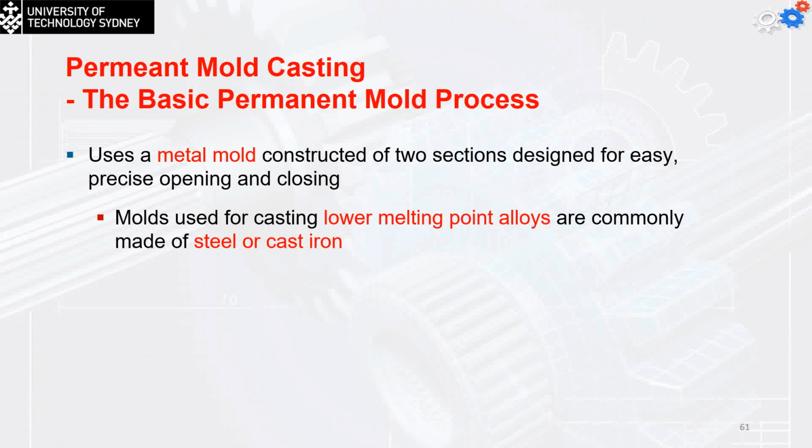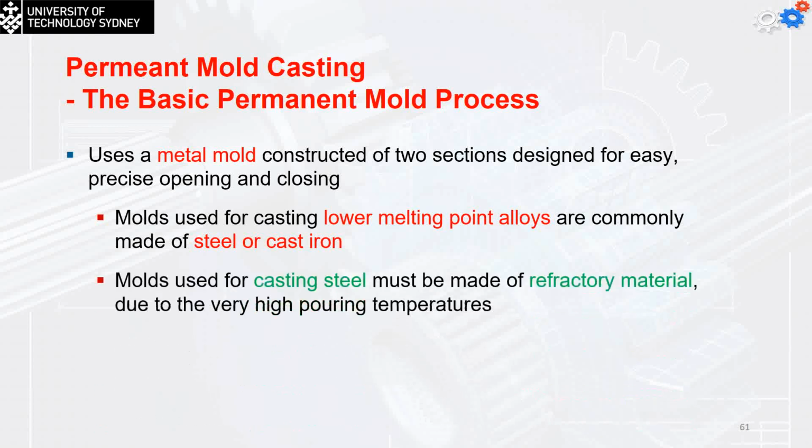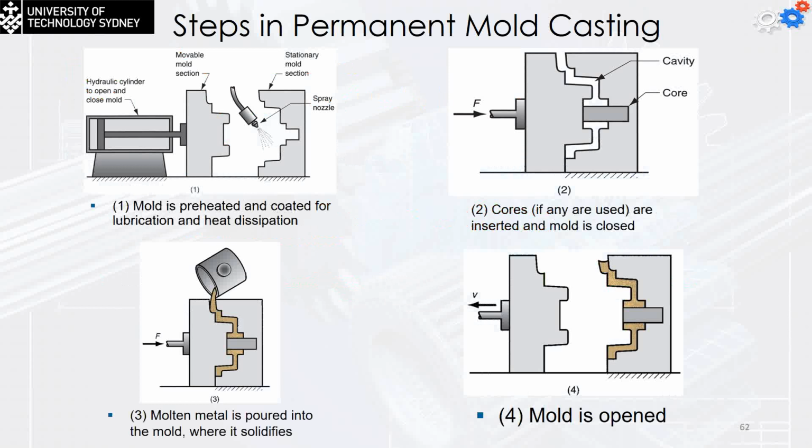This one doesn't have to pressurize the metal inside. So this one is also going to have the problem of shrinkage. With two halves, we have to clean it, add lubricant, close it using pressure to force it, and the point is the metal goes in from the opening there. Fill it with the molten metal, leave it to solidify, take the part off.